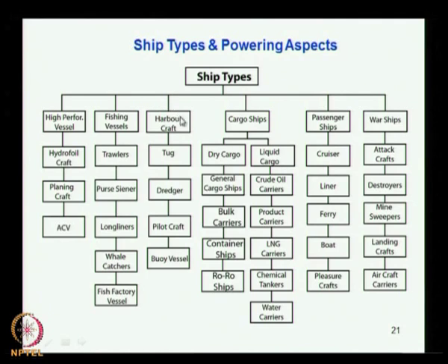Then comes the harbor craft. Among harbor craft, the tug is a major one. Tugs are of different types: ocean going tugs, harbor tugs and all that. Harbor tugs are confined primarily to the harbor region, assisting big vessels to move from the berth or getting to the berth and all that. And ocean going tugs have to go in a free running condition.